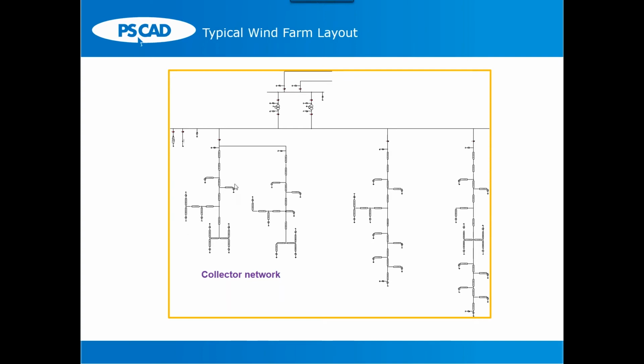So in this particular case, the first parallel branch of feeder 1, I think it has 1, 2, 3, 4, 5, 6, 7, about 9 wind turbines connected to it. We would model all of them in explicit detail, because this is a critical study, especially if you are performing this to verify the performance of an offshore wind farm. So in these cases, in order to avoid doubts, we model at least one feeder in explicit detail.